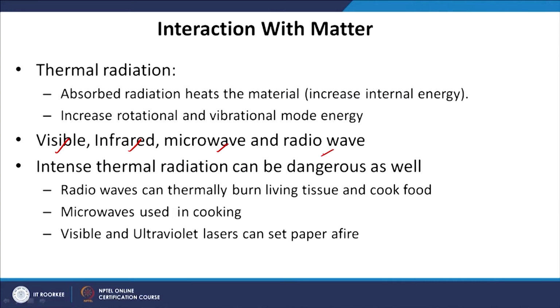On the other hand, there is something called thermal radiation, which is the most important from the heat transfer point of view, and in this category we have visible radiation, infrared, microwave and radio waves. So, all these radiations have long wavelength, greater than 0.1 micron. They are classified as thermal radiation because they are responsible for transferring heat.